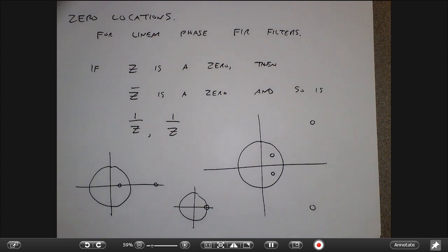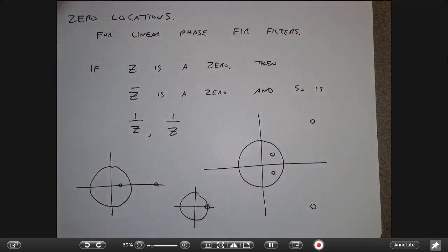And so, in some sense, you could take any linear phase FIR filter and decompose it as the product or the cascade of a bunch of these canonical filters that have kind of one group of zeros each, right? And this comes back to the question of what is the best way to realize a filter in a given scenario, right? So in addition to straight out N taps, polyphase, you could also think about a cascade of filters that correspond to groups of zeros, right? That's another way of thinking about it.